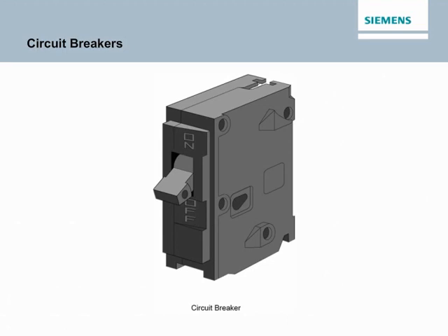All circuit breakers perform the following functions: sense when an overcurrent occurs, measure the amount of overcurrent, and act by tripping in a timely manner to prevent damage to the circuit breaker and the conductors it protects.